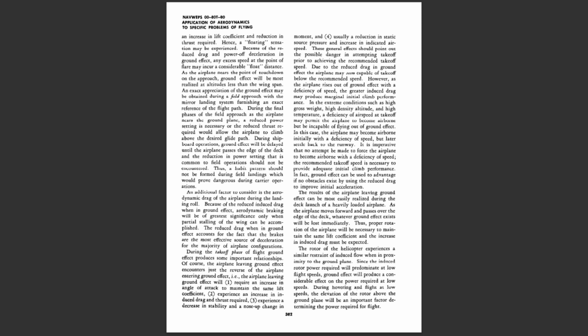During shipboard operations, ground effect will be delayed until the airplane passes the edge of the deck, and the reduction in power setting that is common to field operations should not be encountered. Thus, a habit pattern should not be formed during field landings, which would prove dangerous during carrier operations.